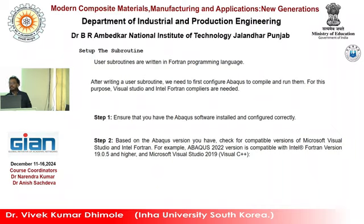Configure Abaqus to run and compile with the proper Visual Studio and Intel Fortran compiler, right? Because the subroutine is nothing but a Fortran file. So we need Visual Studio and Intel Fortran, and for those we just need compatibility. Like suppose I have Abaqus 6.15 or 6.14, then for me Visual Studio 2018 or 19 is okay, and for me Intel Fortran 2014-15 or more is okay. Like that we have to understand the compatibility.